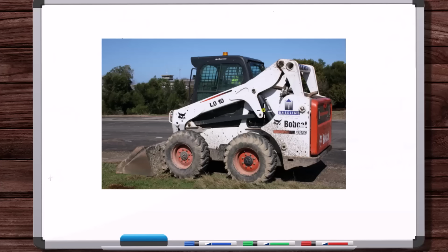Now you might be saying, well, how can I account for all loads? What about the Earth's magnetic field, could that be causing a force on this? What if a bird flies and lands on it, the bird's going to exert a force on it? Okay, let me give an example. I don't design bobcats, but when this is in an operating position, so it has its operating load on the plate, in a lot of situations, designers will neglect the weight of a component in the free body diagram because the weight of the component is small compared to the weights in the links.